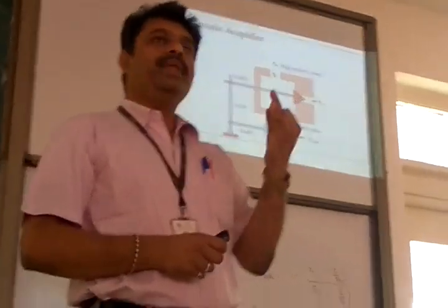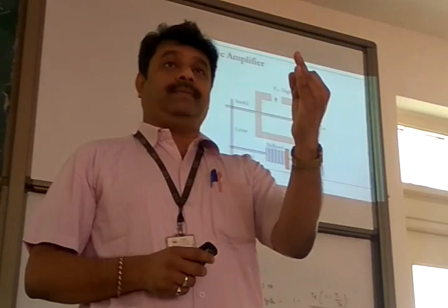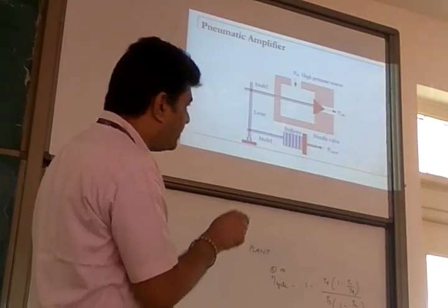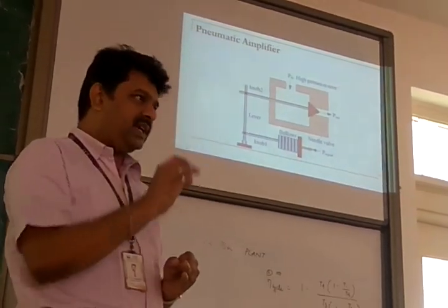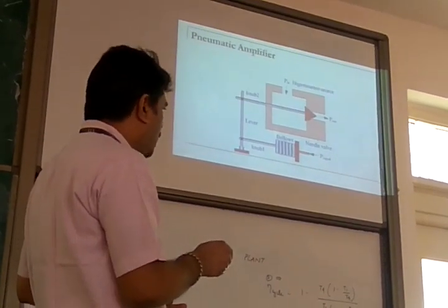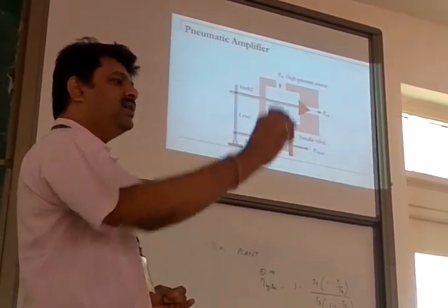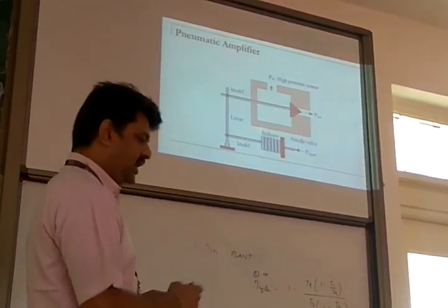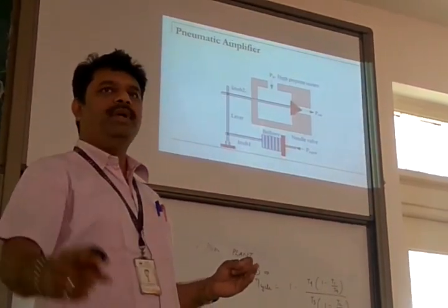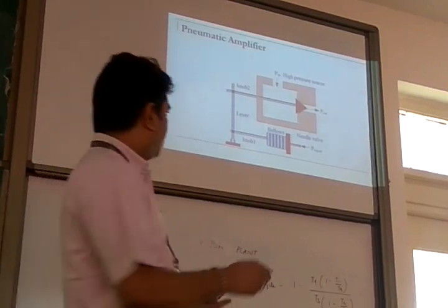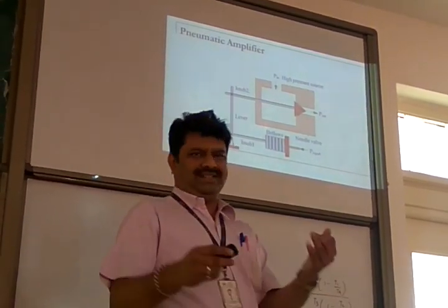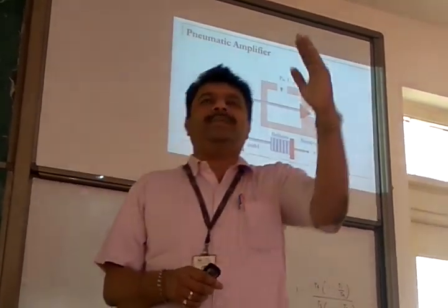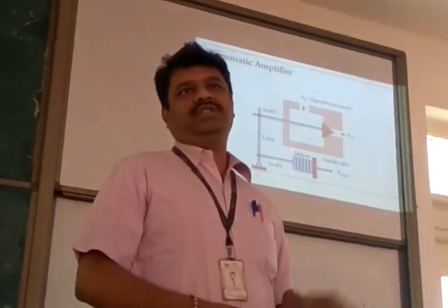2 conditions satisfied. It should reproduce faithfully. That means if I vary the pressure here sinusoidally, here also the pressure variation should be sinusoidal. Increase in pressure, decrease in pressure, sinusoidal. If I keep on increasing, suddenly drop, that is a sawtooth waveform. Keep on increasing, keep on decreasing is a triangular waveform. All these kinds of signals are test signals which we can visualize. That way you vary, same shape I am getting at the output. So there is a faithful reproduction of the input signal at the output.